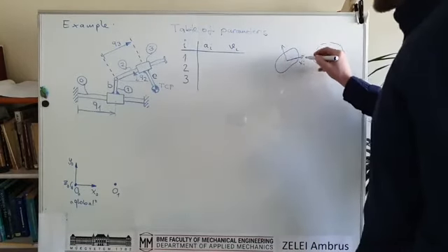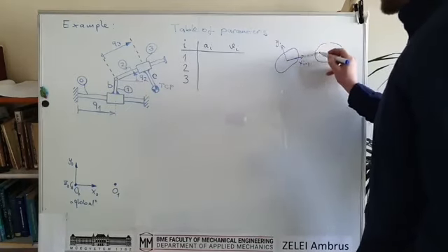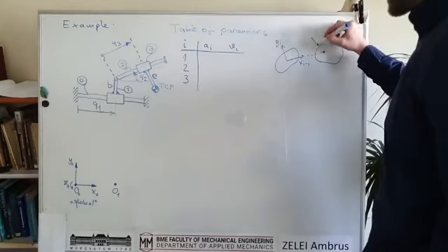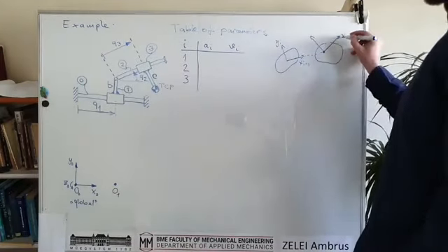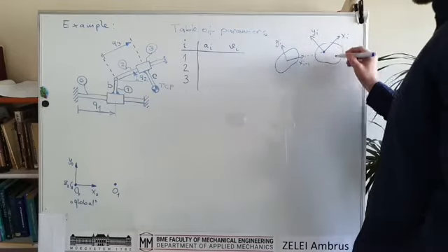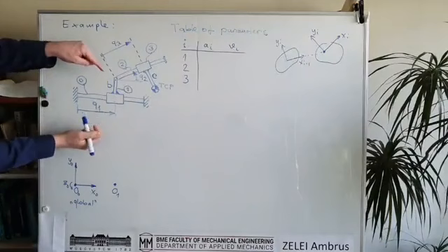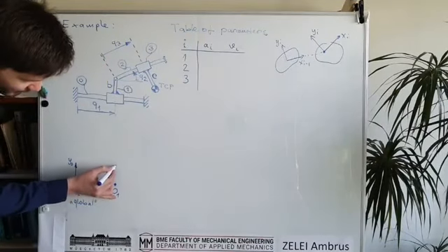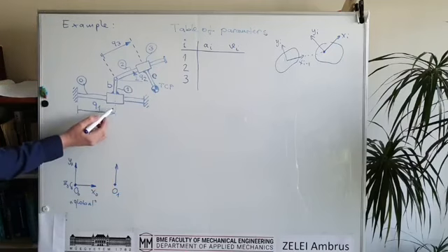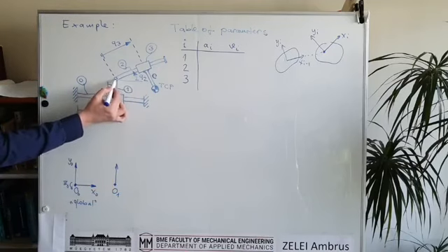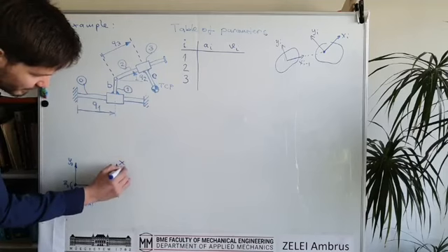So this is x_{i-1} and y_i, and we know that we can only have a transformation along the axis x. Okay, so if we want to move later into this point, the axis x must be vertical, otherwise we cannot have a transformation with which we can move here to this point. So that's why this will be axis x1,